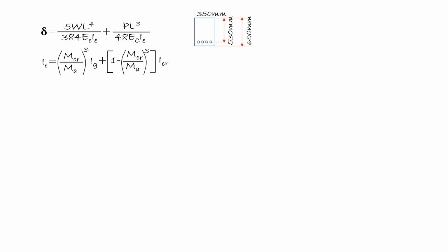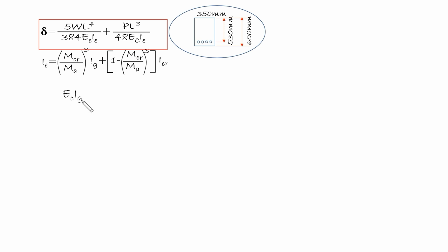For calculation of deflections of uncracked prismatic members, the usual formulas for elastic deflections may be used with constant value of EcIg along the length of members. However, if a member is expected to crack at any section, or if its depth varies along the span, a more rigorous calculation is necessary. Rigorous calculation includes calculating the effective moment of inertia instead of using the gross moment of inertia in this deflection equation.